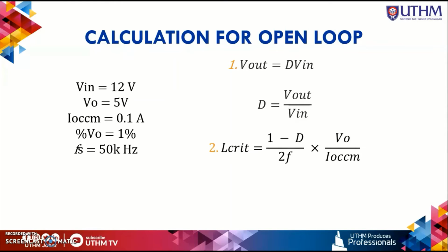Then to calculate the value of the inductance, we will use this formula, which is 1 minus D, which is duty cycle, over 2 times frequency times Vout over IOCCM.